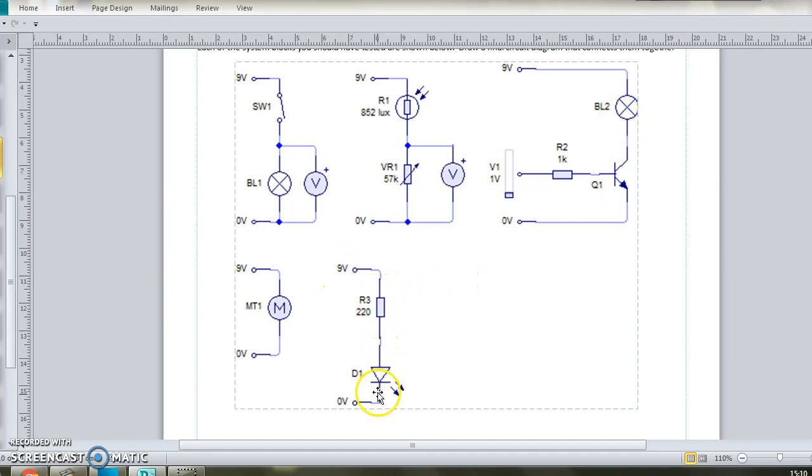And separate to that, I had an LED, because the LED is just going to be on all of the time to bounce light off the black and white surface so that the LDR can get a better reading from whether or not it's above the black line. So I've got 5 different mini circuits and I need to combine it into one circuit.